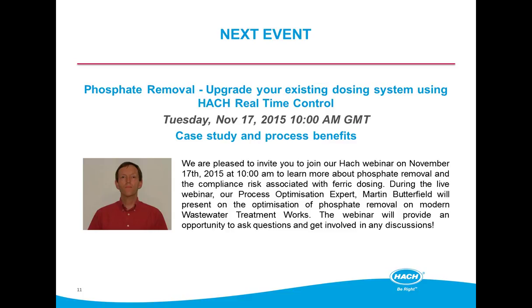So to make sure that the system is as robust as possible, we have an ammonia measurement on the outlet of the plant, which can then correct for any anomalies that may affect the biology, which you couldn't account for in every event with a biological model that we have in the controller.